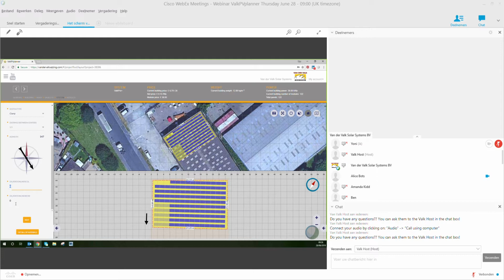The dilations here are the same as we saw in the simple mode, so you can add these if you want to. They will only be added automatically if you exceed the maximum row or number of rows before thermal expansion gap is required. When you're happy, you click next. Foundation is fixed, the color is fixed. Again, you can choose your power optimizer, micro inverter clamps here. Add tiles if you want to, and side shields if you want to.